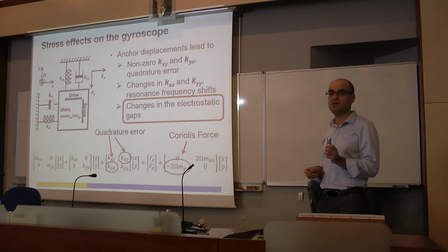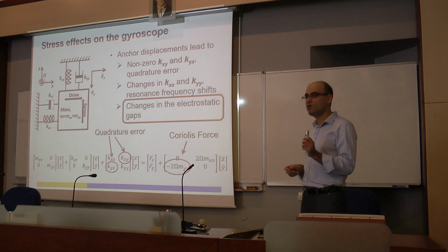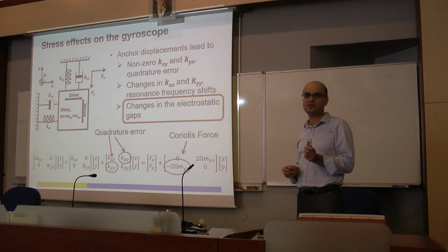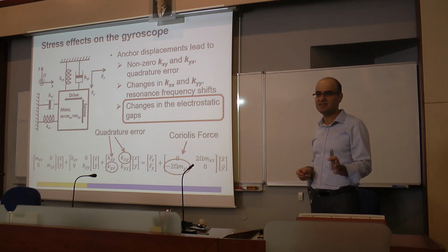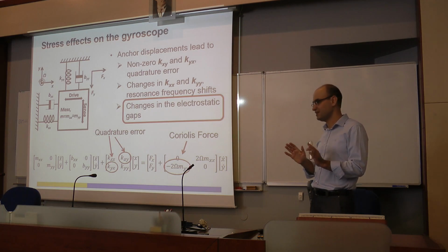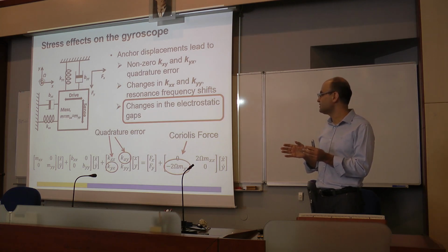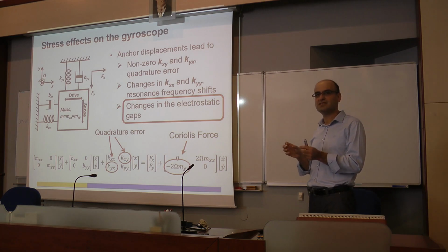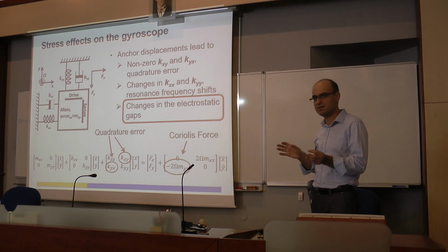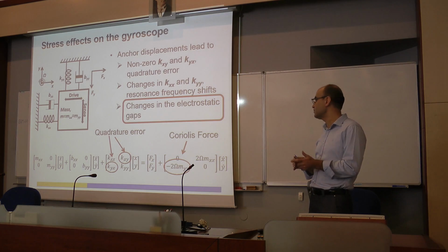The gyroscopes, one main principle is they work on phase-sensitive demodulation. In a gyro, everything is phase, so you have to pay attention to phase extremely. Because some signals are 90 degrees out of phase from your main signal, if you do a phase-sensitive demodulation, if you multiply the signals properly, then you can get rid of them.